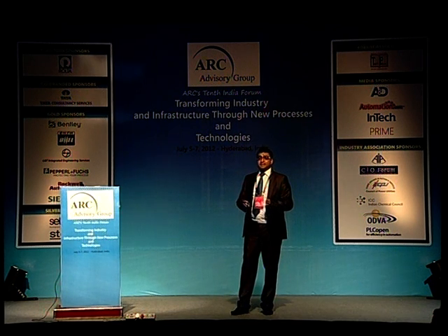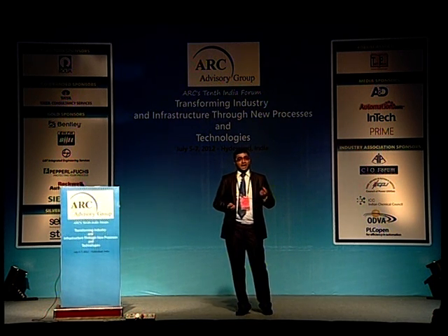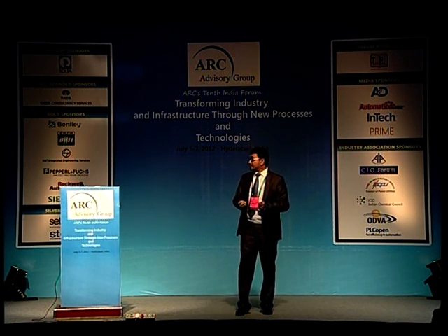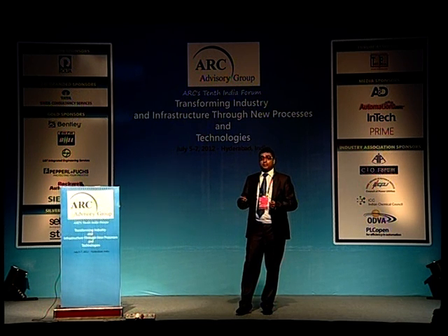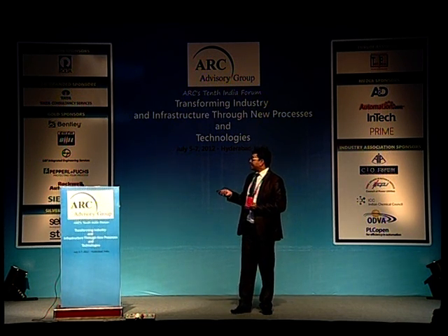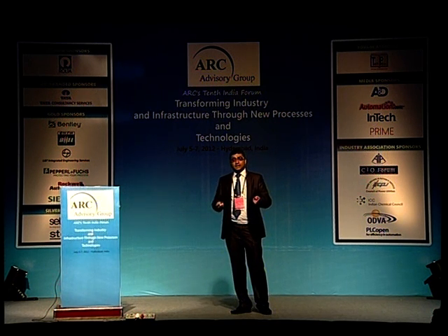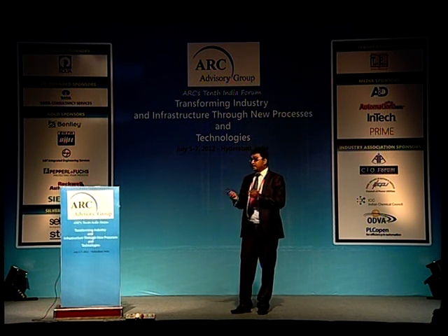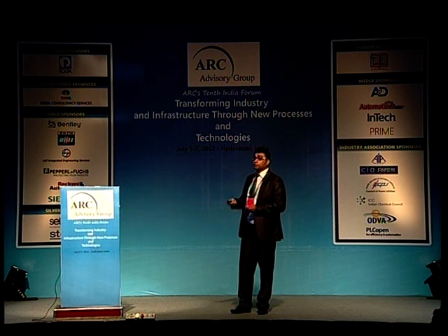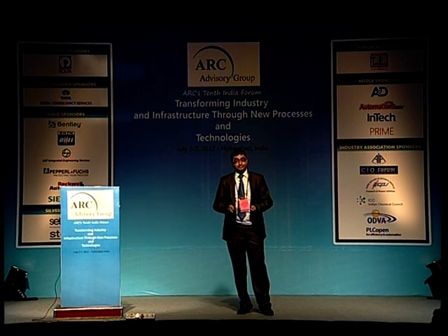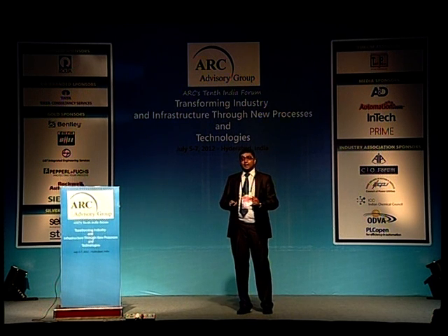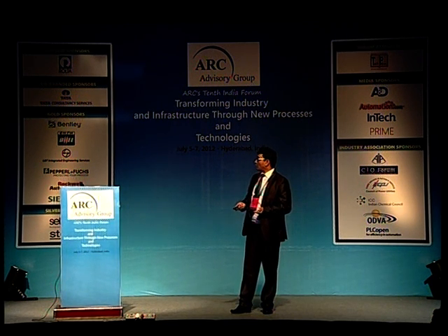But the first important thing is that any calculations or optimization solutions, because this is an online software solution, take data from the existing DCS, and all the inputs required for Pardo are taken from the DCS. Unless you validate the data or measurements, the results coming out of the system are also not reliable. So we validate the measurements, and by doing that we improve the quality of the measurements. The power plant C&I maintenance group, the control and instrumentation maintenance group, can have reports of the measurements which are implausible. That helps to improve the quality of the measurements.